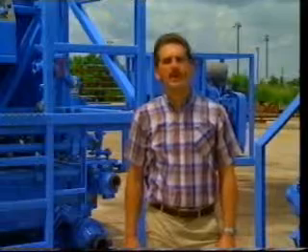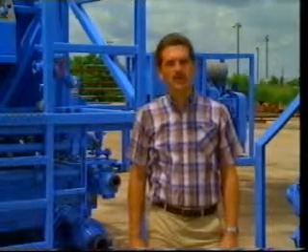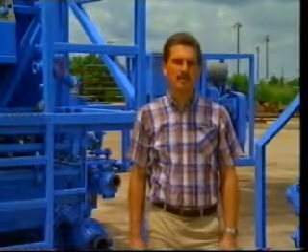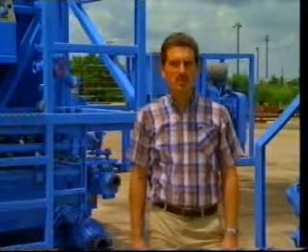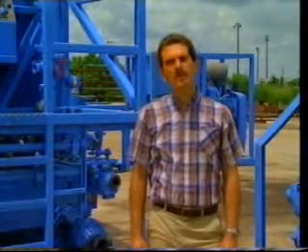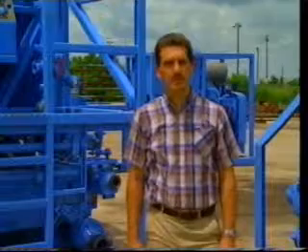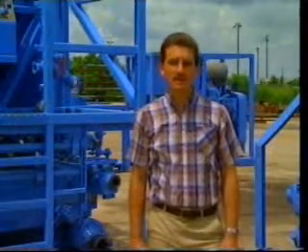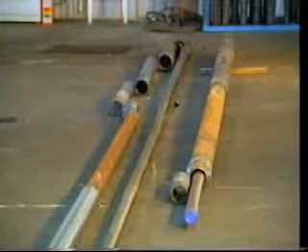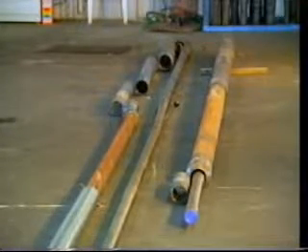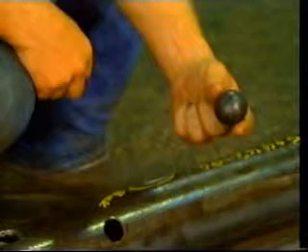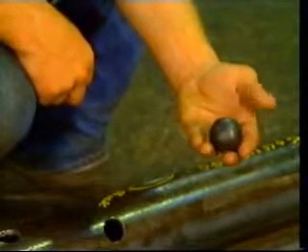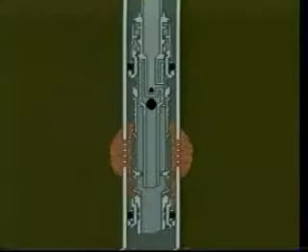Note that when gravel packing low bottom hole pressure wells using the setting tool crossover assembly, reversing pressure is exposed to the formation. This adversely affects the ability to reverse excess gravel from the work string and may lead to formation damage. In order to avoid this problem, this setting tool crossover assembly can be modified by running the tool with a circulating ball in place at the bottom end. The job procedure remains the same except for the reversing sequence.